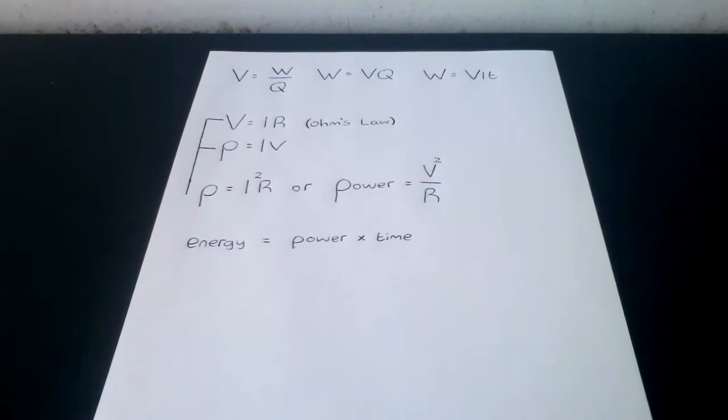We can see that the efficiency will be greater when the voltages are high and the currents are low. For example, if a power of 20 MW is to be delivered down a cable with resistance of 100 ohms, is it better to use a current of 20 amps and a voltage of 1 MV, or a current of 2 amps and a voltage of 10 MV?